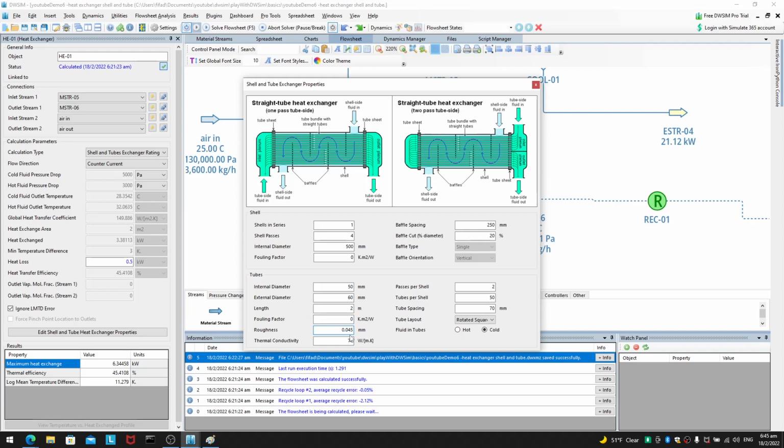And for calculation of friction factor, there will be some roughness as well, which plays an important role for turbulent flow, and that will help you determine a friction factor from the Reynolds number. And once you have a friction factor from the Reynolds number, you should be able to get some Nusselt number correlation.